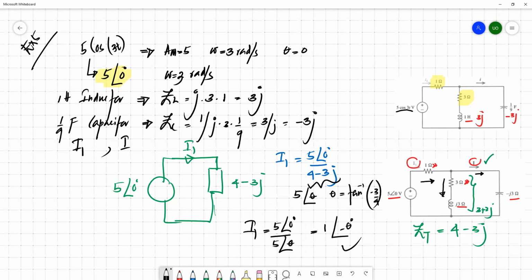So from this onward, it's something related to mathematics. So you can use the mathematics knowledge and come up with the exact value, but keep in mind, the ultimate value should be in phasor. Phasor means a kind of a magnitude and angle. So then whatever the values in the rectangular form, A plus JB form, should be converted into polar and simplified, and take the value in R theta form.